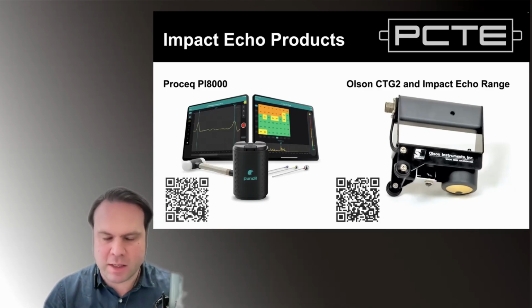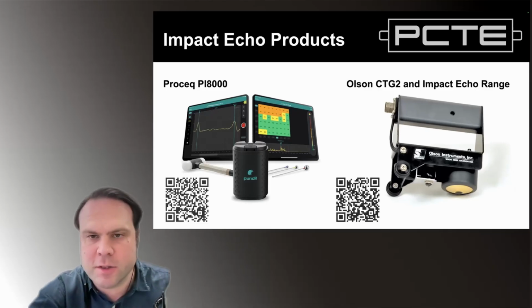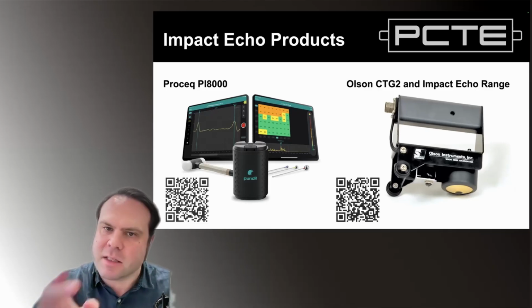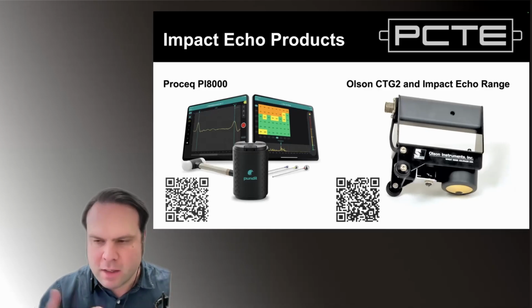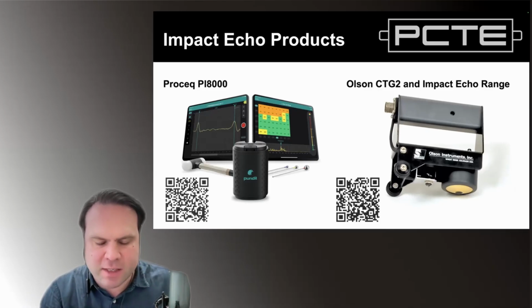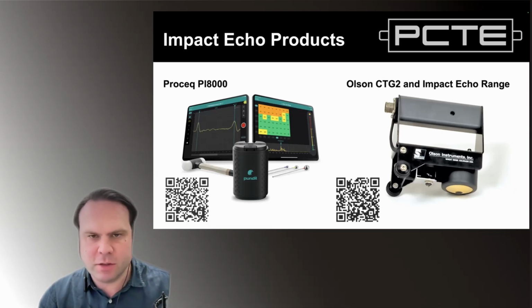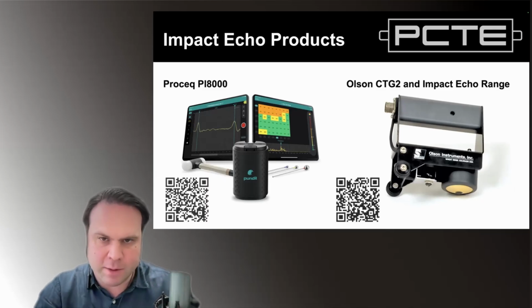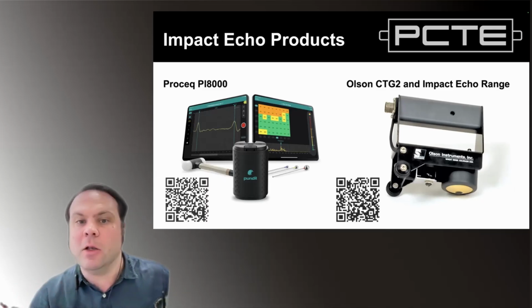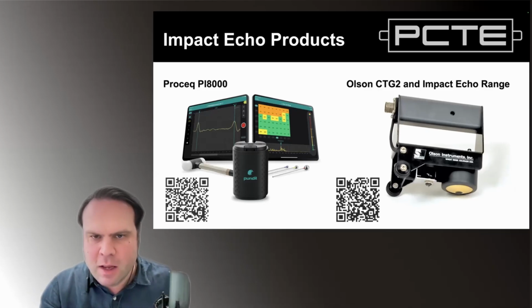My thoughts are, firstly, yes, it probably is a good method, but your research is going to be more able to answer some of the questions about what happens. Something that we always do with non-destructive testing, if you haven't done a lot of this kind of testing before, is try and compare a known situation to an unknown situation. So maybe the structure before the freeze thaw damage to after the freeze thaw damage, and look for what change will happen. Now, if I was going to theorize what's going to happen, I think you're right.